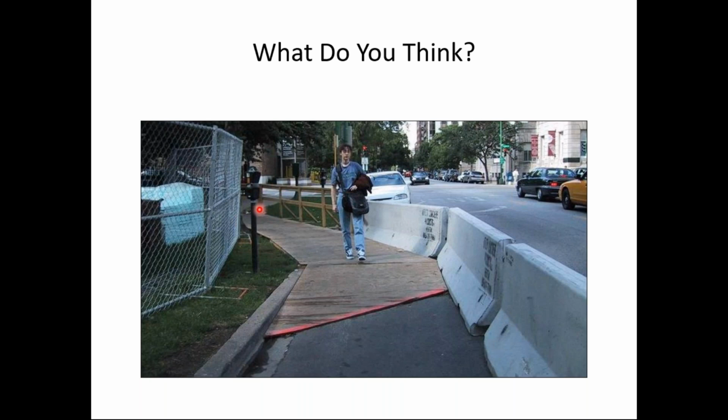which I think is good. And that's probably okay. If it was my project, I would probably put a toe board or kick plate down here as well. That's detectable. And then they have the separation from traffic. They're using temporary traffic barriers. That's good. But recall, these need to be interconnected and interlocked. These are not. So these are probably not going to behave as a crashworthy device. These need to be interlocked and connected and continuous with one another.